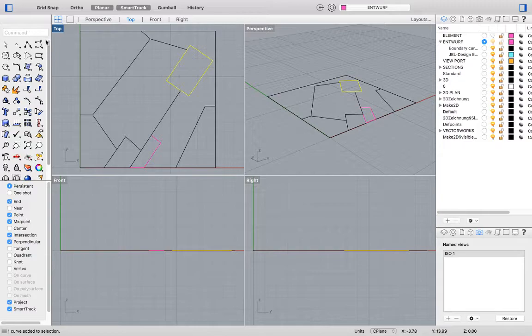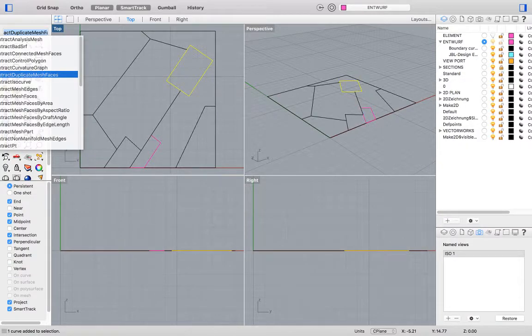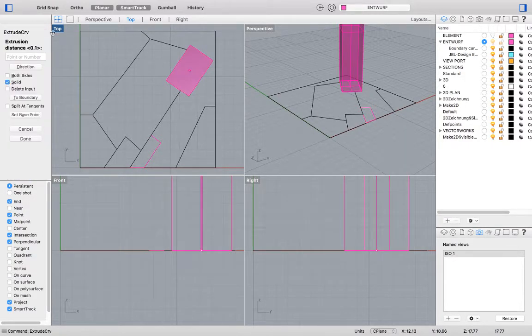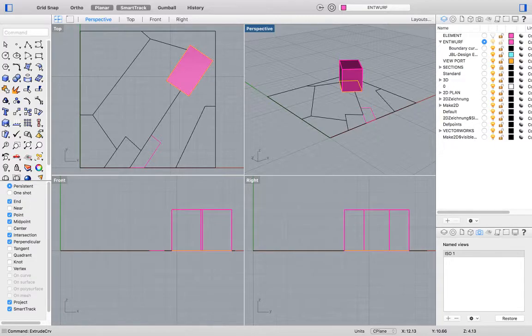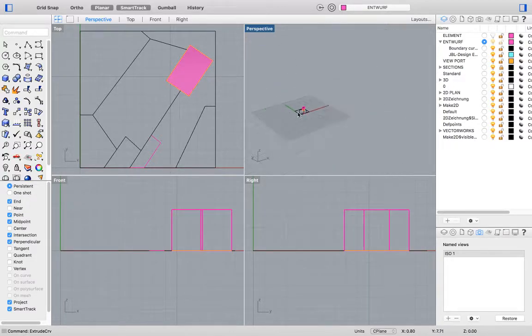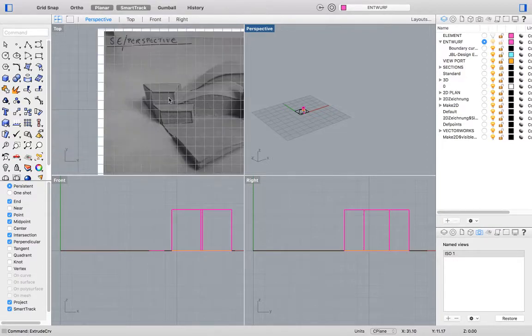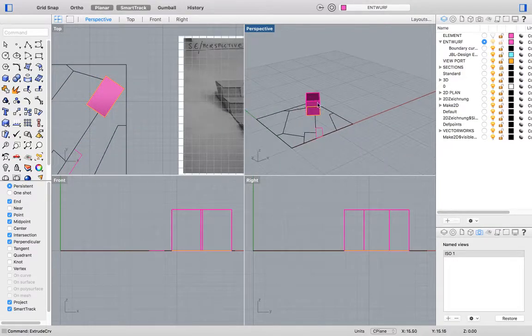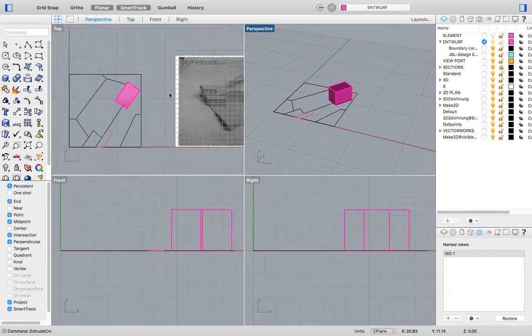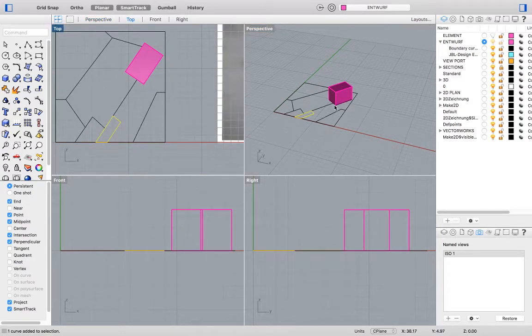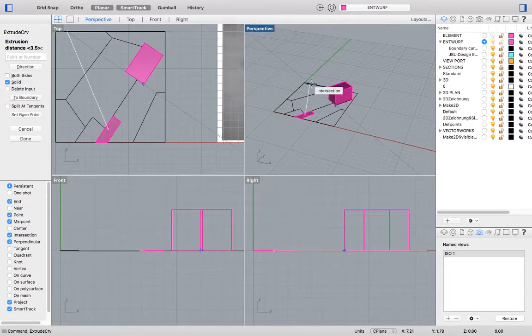Okay, so we're going to extrude these volumes. First one is this one, by 3.5 meters. So we type the command extrude, curve, and then you'll see this option appear. We type in 3.5, enter. So there we go. We've now got our first object that's extruded, which is this one here. Next is these two, so this one, repeat the command is hit enter key.